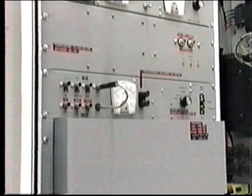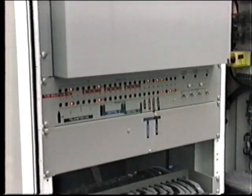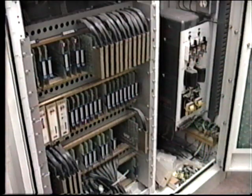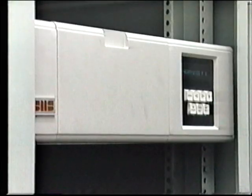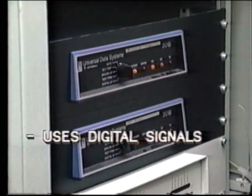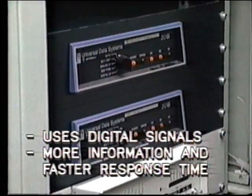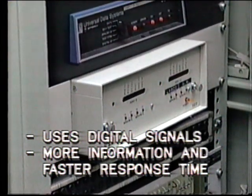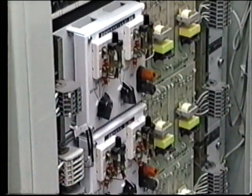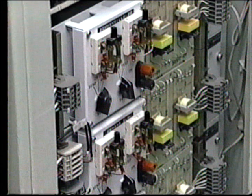As an improvement on telemetering, SCADA systems developed utilizing integrated circuits to provide much faster response and handling of data. Much of this equipment, installed in the 70s, is still in operation, and no doubt creating maintenance work for many of you. The more recent SCADA systems are microprocessor-based, using digital signals. This allows for handling a far greater amount of information and at faster response times. Moreover, the ability to program the software for each specific application means that the system can be made to perform many more useful tasks than the earlier systems.